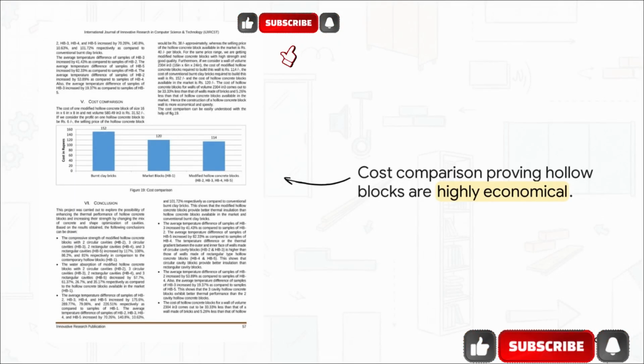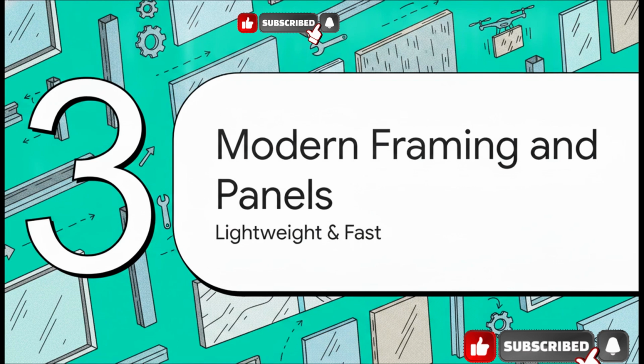And it actually gets better. Hollow block systems aren't just lighter and more energy efficient, they are significantly cheaper. Using hollow concrete blocks can be up to 33.3% more economical than traditional burnt clay brick masonry for the exact same volume of wall. You get a higher speed of construction, way less weight, better insulation, and it just costs less. It's a win-win. Section 3.